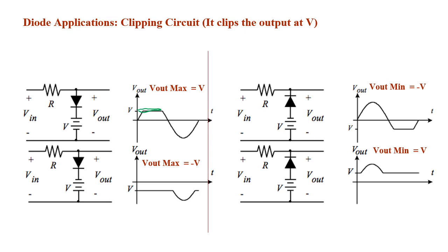then you can maybe cut open the circuit here. So when the diode acts as an open circuit, what you're going to measure to evaluate the output is the voltage across R and the voltage across Vin. So the output is going to look exactly like Vin. Notice that in all 4 circuits, the input voltage is actually a sinusoidal signal. So it looks like this.